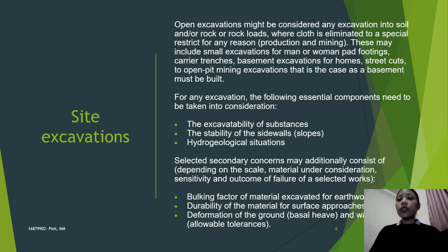For site excavations, it is really important that proper measures are taken and that they use proper reinforcement while doing the excavations, so that we have no soil falling into the trenches while they are digging and so forth.